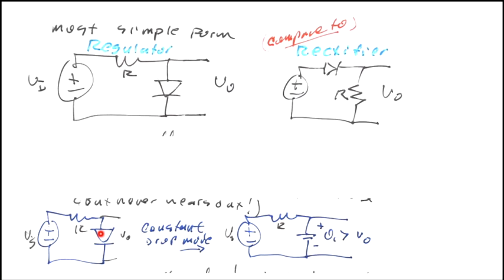And what this regulator is also saying is if we think about the constant voltage drop model, it's as if we've replaced this diode with a battery, and a battery is a DC source that doesn't change much. That's like what we've done with this diode, except this diode can't generate any power, but it can support a constant voltage of about 0.7 volts.